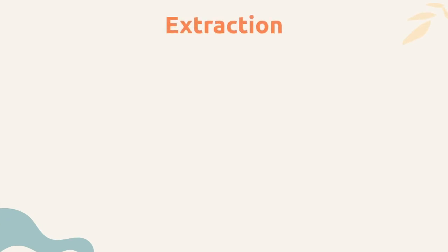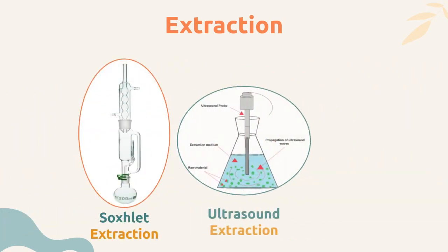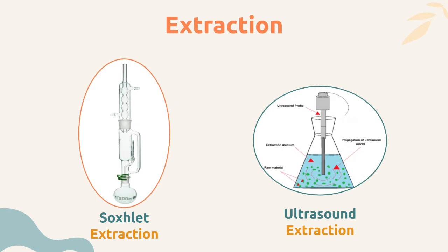In terms of the extraction process, we reviewed two setups that can be used, the Soxhlet and ultrasound extraction. The Soxhlet extraction system is a lab-scale conventional technique. However, the ultrasound extraction system is a great alternative as it solves the issue of time, solvent, and power-consuming techniques.